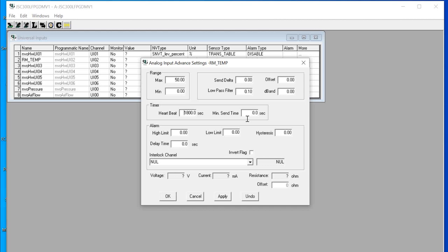So you use the multimeter to measure to make sure whether it's a hardware issue, or a wire signal issue. Make sure of this, then you see which way to solve it. If it's a sensor issue, I think no. Another, some sensors can use AC or DC, right? If you use AC and you see the reading fluctuate, better change to DC as the power supply.